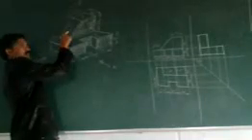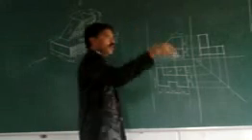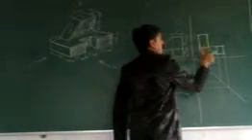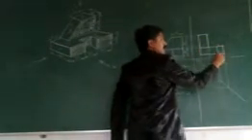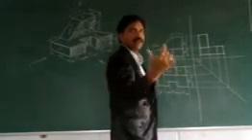So this is the L shape, and this is the thicker line also. Why? Because there is a split from the base to the wall. So this is the base, and this is the wall. This line is going to here, and the joint is clearly visible from wall to base. And this dotted line meant for the groove is not visible from the left side direction.